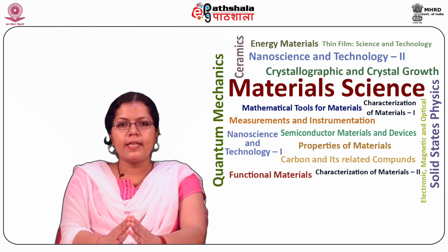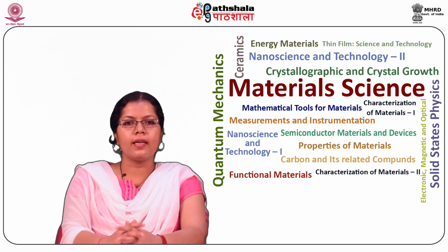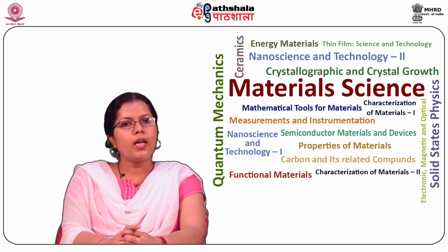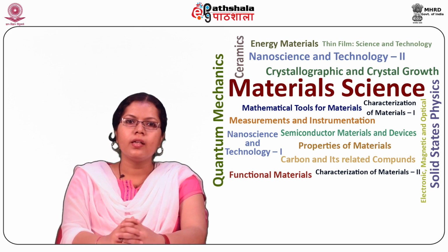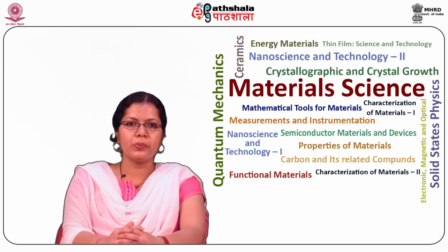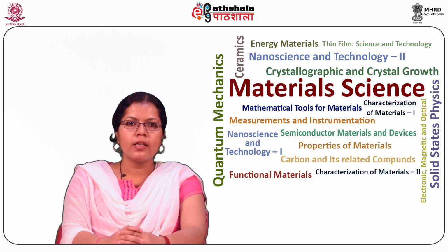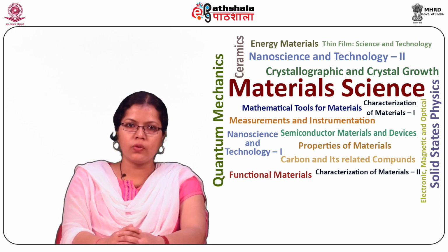The moving coil is connected across the voltage and therefore carries a current proportional to the voltage. A high non-inductive resistance is connected in series with the moving coil to limit the current to a small value. Since the moving coil carries a current proportional to the voltage, it is called the pressure coil or voltage coil of the wattmeter.